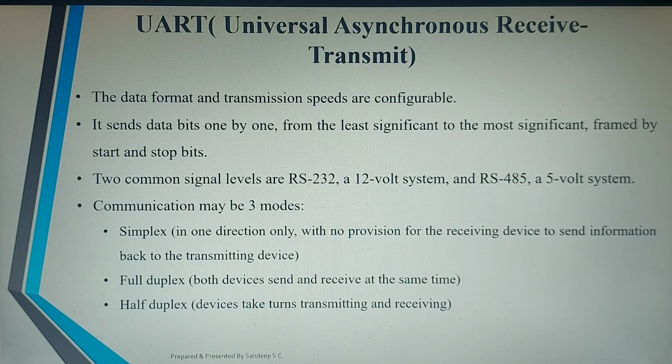It is serial, so serial data transmission. One bit at a time will be sent one by one. The bits will be sent one by one from least significant to most significant, framed by start and stop bits. So there will be a start bit and a stop bit, between which you will have 8 bits of data, sent from least significant to most significant bits one by one.